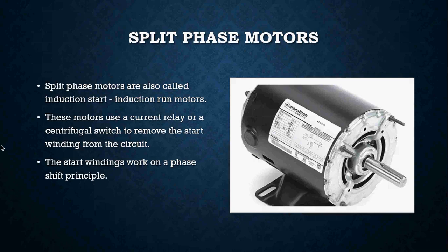The next one that we're going to get into is your split phase motor. These guys are obviously a little bit beefier. These guys can be used as your indoor blower. They can be used as condenser fan motors. They can be used in many different areas of the field. So your split phase motor is also called an induction start, induction run motor. I don't normally call it that. I'm just going to call it a split phase. But usually if you want to really sound smart, you say induction start, induction run motor. Sometimes people look at you like you have three heads.